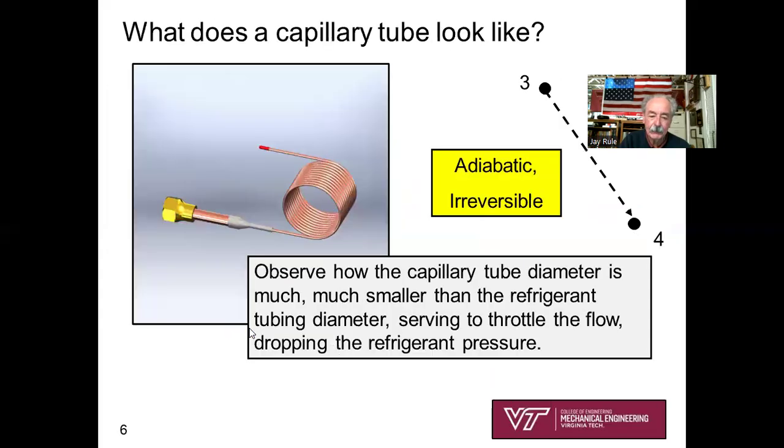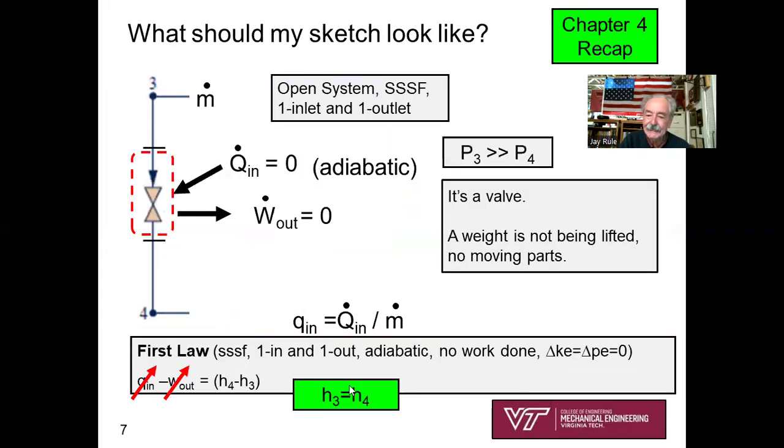And what made that so easy? What made that so easy was the statement of the first law for the expansion valve for a refrigeration process, h3 equals h4. So do you see that h3 equals h4 is a statement of the first law? It's not just a formula you put down on your formula sheet.